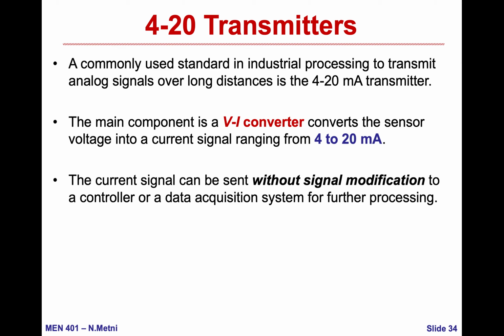So what we will do is that for any voltage equal to 0 in the sensor, I will convert it to a live 0, which I will set equal to 4 milliampere. So now my 4 milliampere corresponds to a voltage equal to 0. Now when I read a current I equal to 0, I will say that there's a faulty connection in my system.